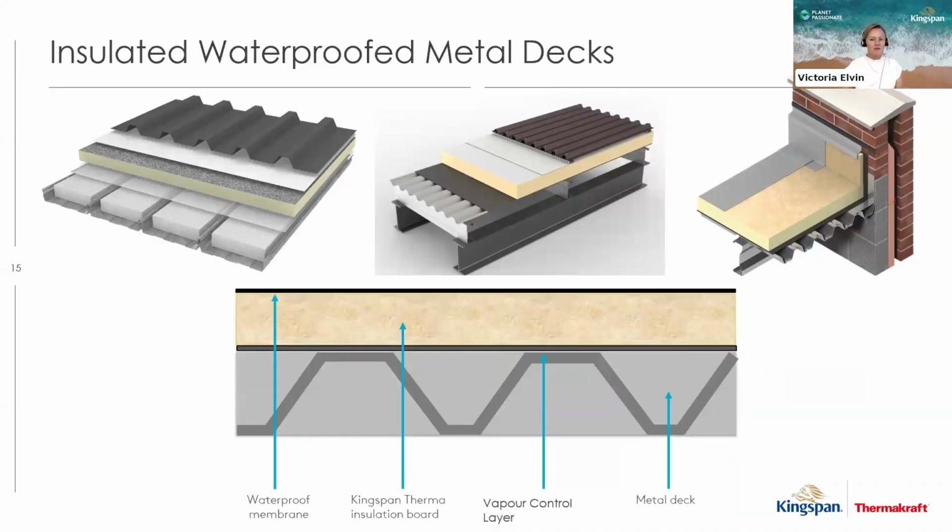A warm roof design requires a continuous substrate. A metal tray substrate is very popular as the building is enclosed as soon as the carrier tray is laid, and the carrier tray can span further than plywood can. A vapor barrier again is installed between the substrate and the insulation, and that may either just be tape on the joints of the metal tray or could be a full vapor barrier that's laid over the metal tray.